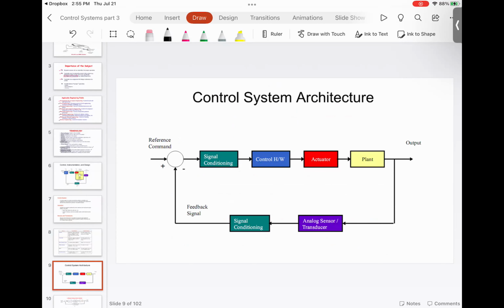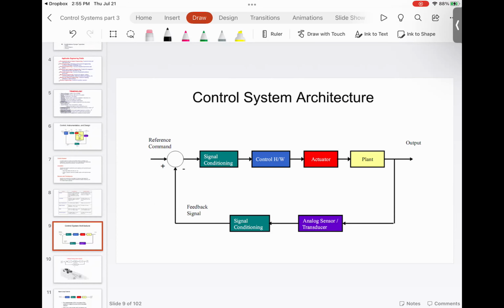This is the classic closed loop control system architecture, wherein you sample a certain part of output and you feed that output all the way back to the reference. You compare it with the input, that is called error. That error gets fed into control law, and then you use an actuator to control the plant. And you do it recursively till you meet particular performance specifications.